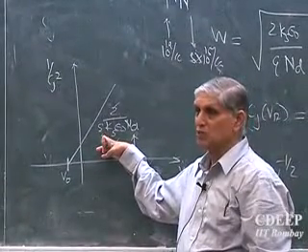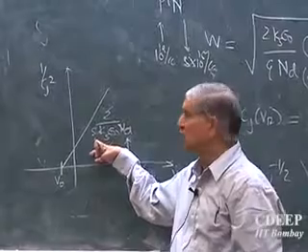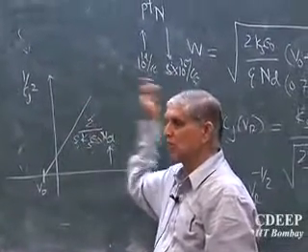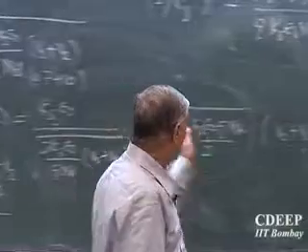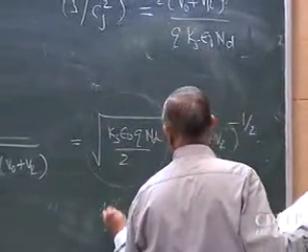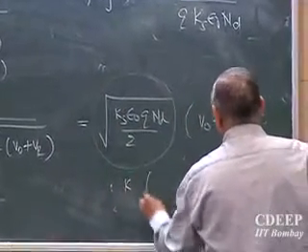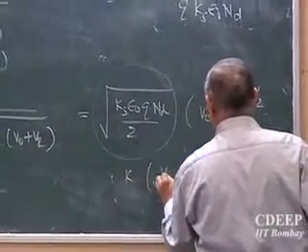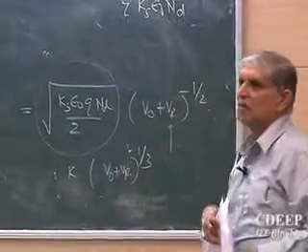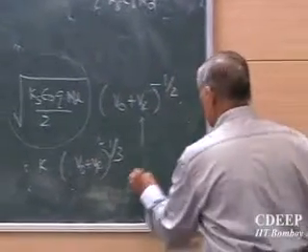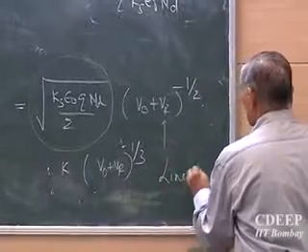In reality, if it's not so, one has to evaluate the relation between C and V once again and find it from there. Of course this will change some constant K, and the exponent will come to the power minus 1/3 for linearly graded junctions, which we'll do just now if possible.